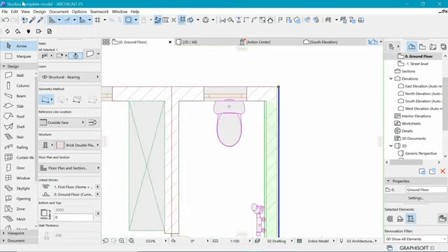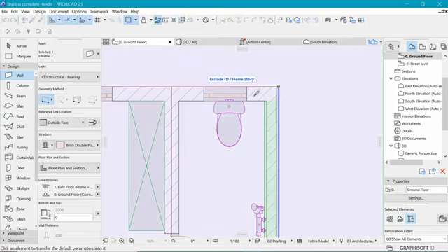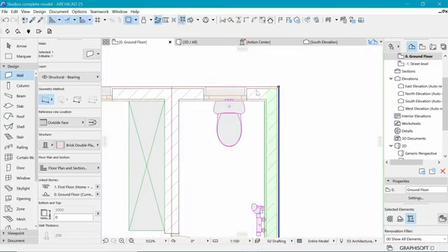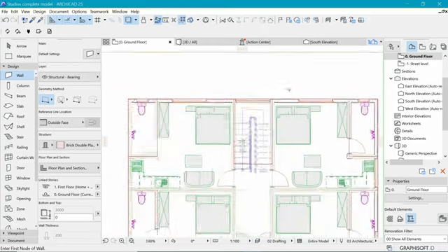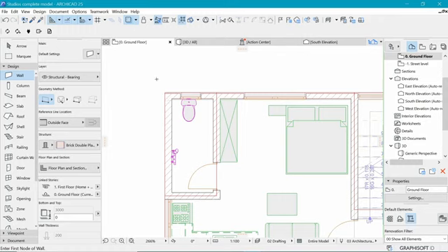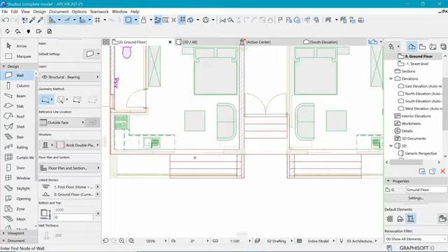So for that, we will pick up parameters, we click on this wall, and then we click inject parameters, and we inject those parameters in this wall, and you can see that it actually changes to that. And we click inject again, and we inject those parameters in this one as well.